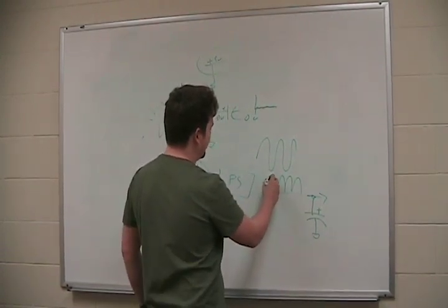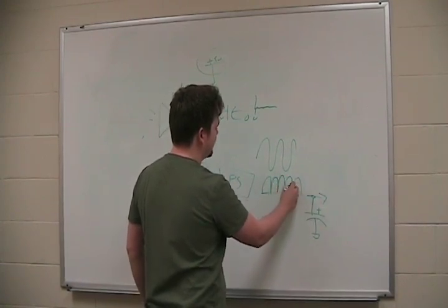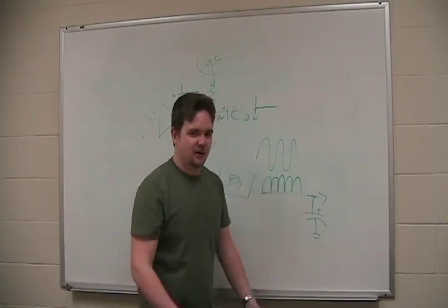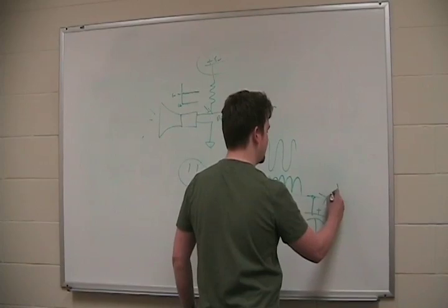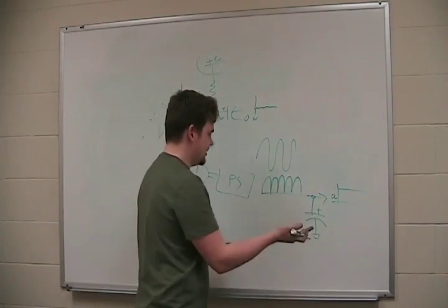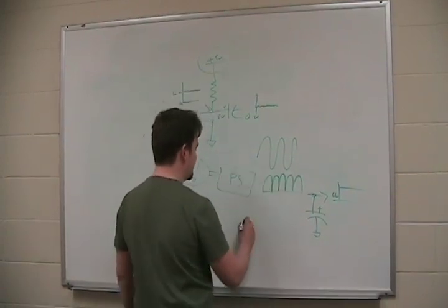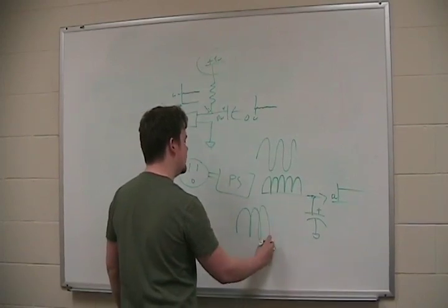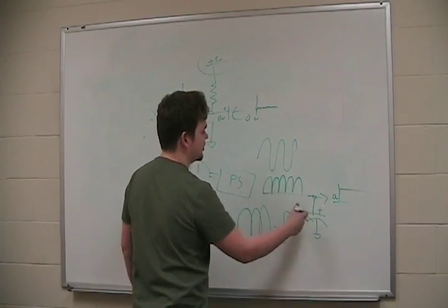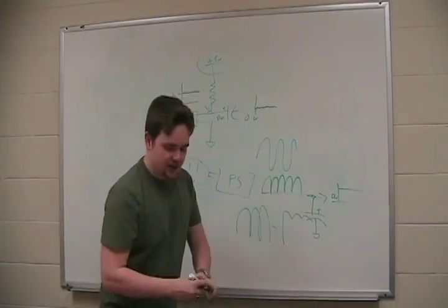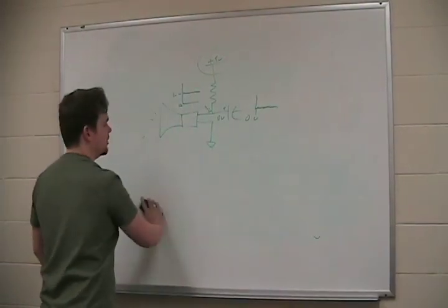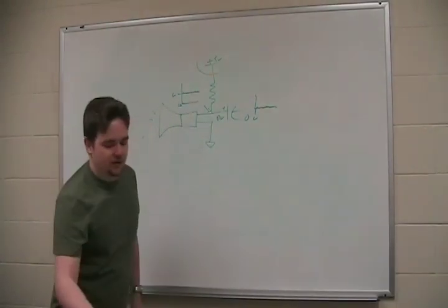So you see that we're getting positive. If we're looking at a power supply after it's been rectified, we're still getting some bumps here. We don't want to use that. We want a nice, straight, or as straight as we can get it, DC supply. So what that capacitor does is change that, because it charges and discharges and charges and discharges. That's all stuff we can get into later, but I'm just trying to go over with you certain reasons why you'd use a capacitor.